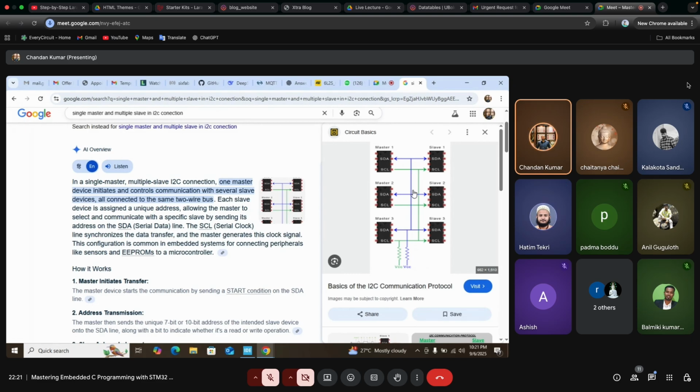And if it is not performing any task, it's free, then it will communicate with slave D. Similarly, every master will check if the slave is free or not, and if it is free, it will communicate with that particular slave in the same manner. It will lower down the clock pulse and send the signal to that particular slave. Then that particular slave will communicate with it.